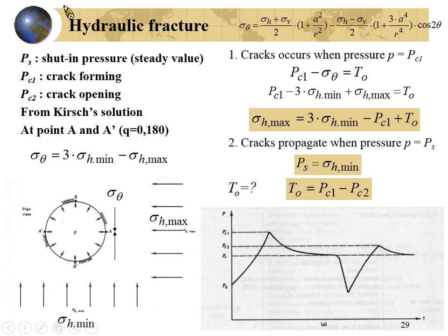So can you distinguish the difference between the orientation from the borehole breakout and the orientation from the hydraulic fracturing? One is to increase the pressure inside the borehole for the hydraulic fracturing. And the borehole breakout is induced by the high deviatoric stress, which makes the rock crush.